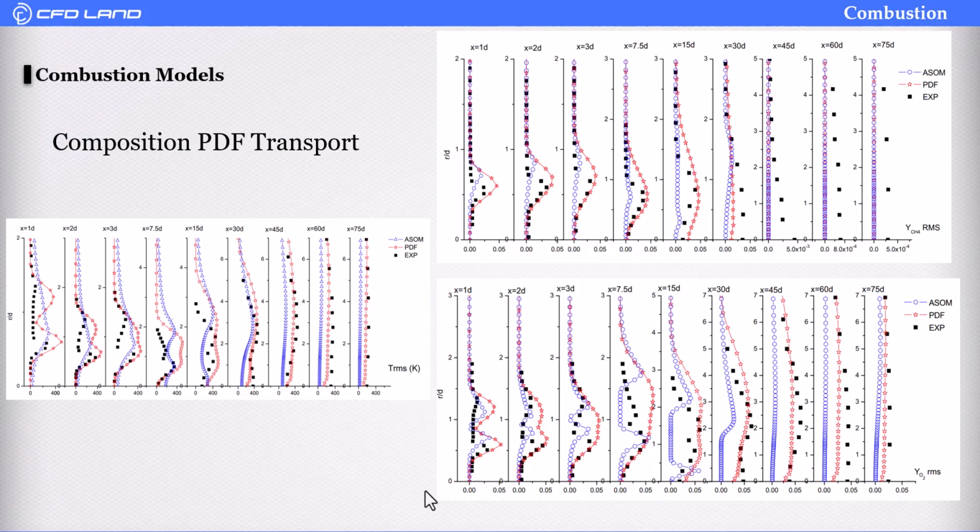Another limitation of this model is that it is only used for pressure-based solvers. And discretization in this method is done in 2 ways, Lagrangian and Eulerian. The Lagrangian one is more accurate, but needs more time to converge.